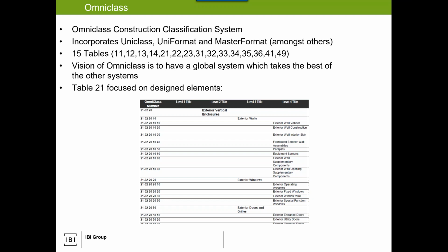The other one could be if I'm feeding cost estimations. Let's say we're using that BIM use, and we'll see, actually there is a use map about that later on to look at. But if we're doing that, you're going to model. At some point, you're going to grab a static snapshot. Somebody has to validate the data. The data has to be validated to the classification system. It has to be fed through an export process into the cost estimating system where the estimate happens and then validated back. Again, it's all about workflow.